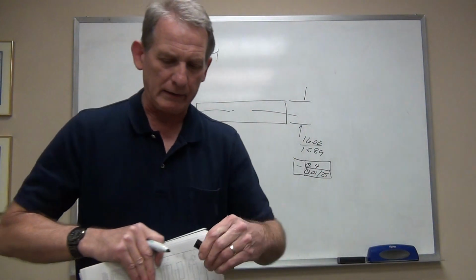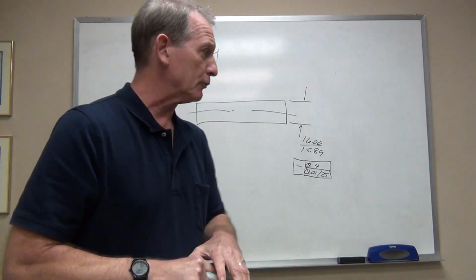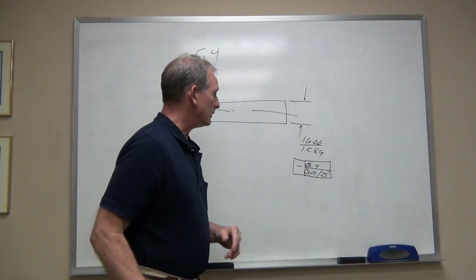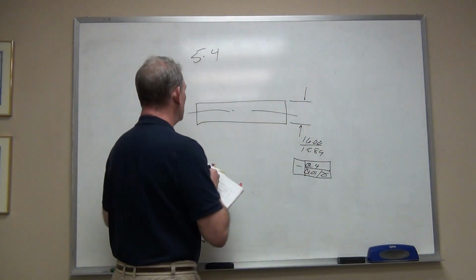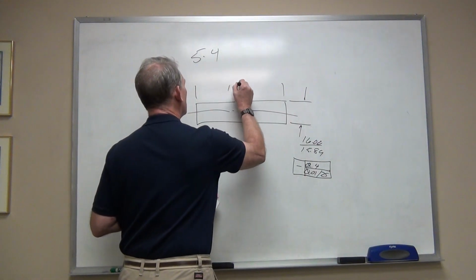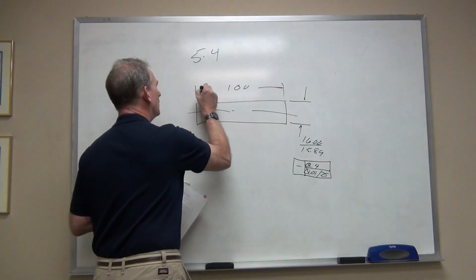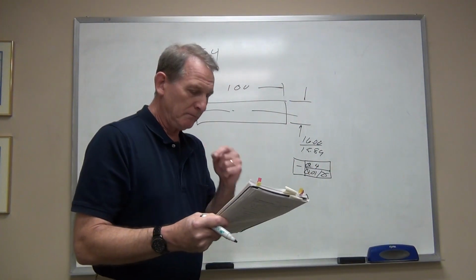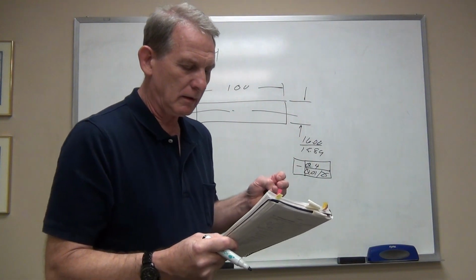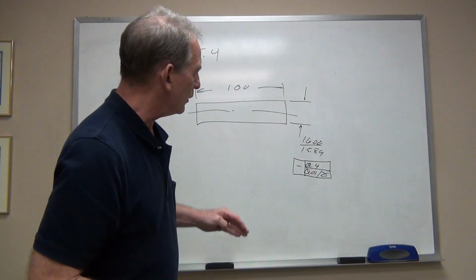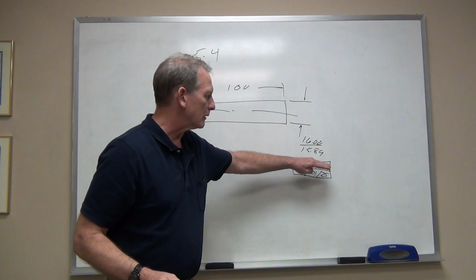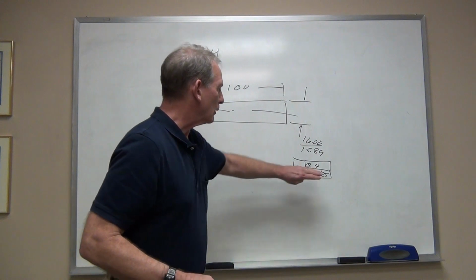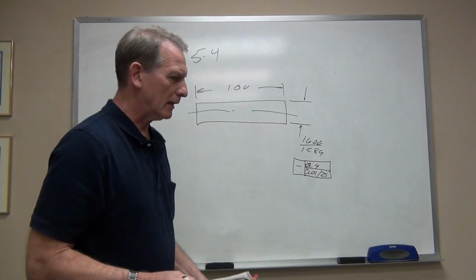Okay, bear in mind again that these examples are meant to be metric. So in this instance, we have a long shaft that is 100 millimeters long. That 100 millimeters is roughly 4 inches, so it's not super long, but when we look at this composite control, we always read them just like we would read a book. We read the tolerance information from the top down. So we read this one first, and that says that